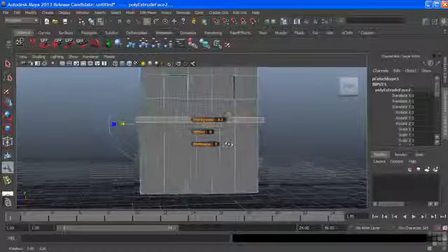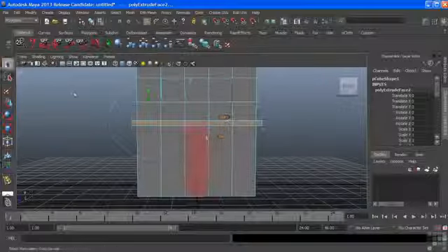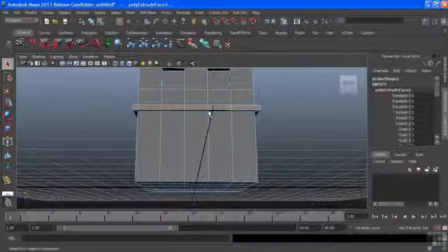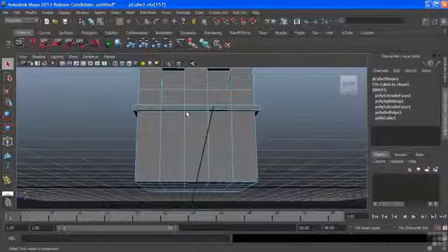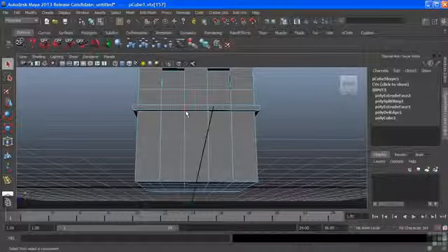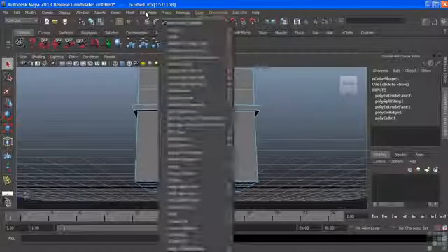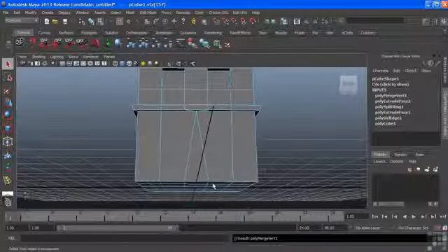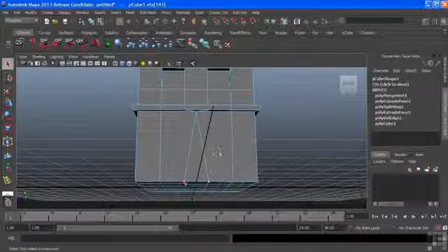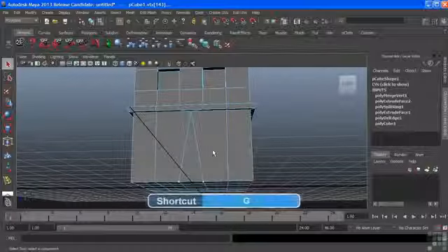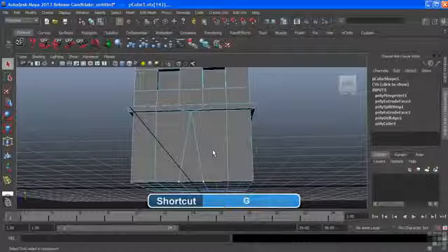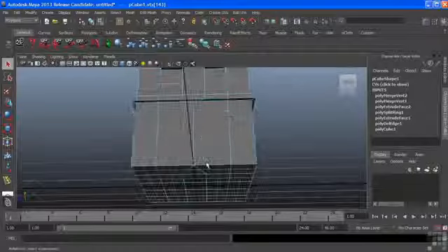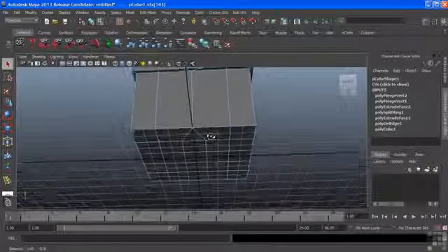Next, we'll add a door. Now right click to go into vertex mode, and I want to select the vertices underneath that concrete slab that we just extruded. I'll grab those 2 and go to Edit Mesh, and I'll use Merge to combine those vertices. And I'll do the same for the bottom 2, but this time I'll hit G on the keyboard to repeat the last command I just did, which was Merge Verts. Now notice too that the bottom there is also being merged.